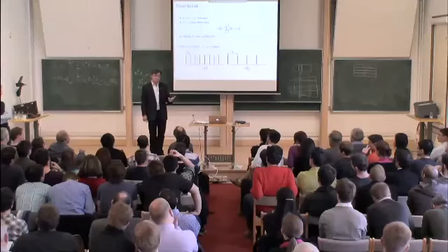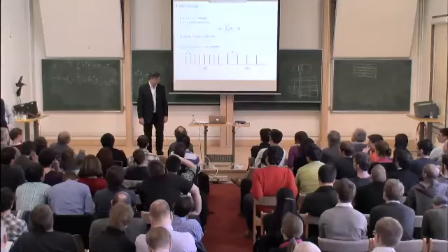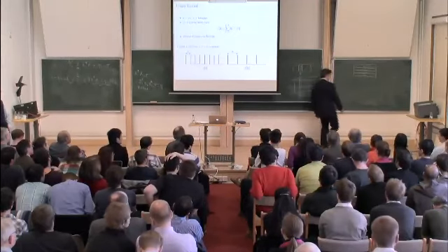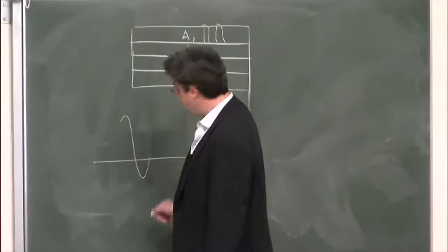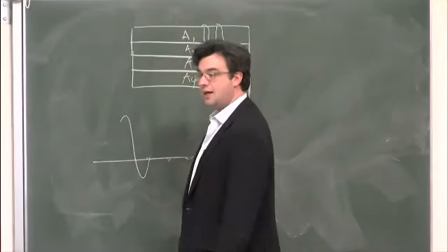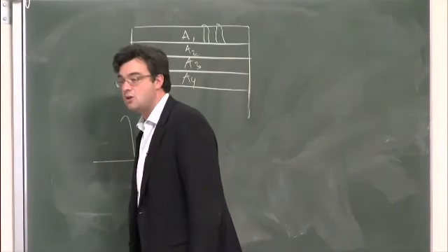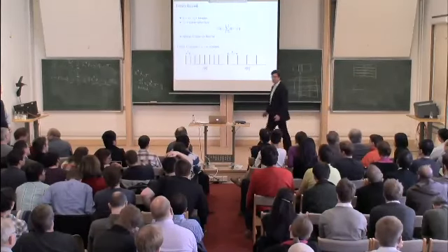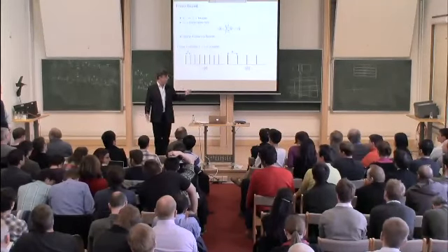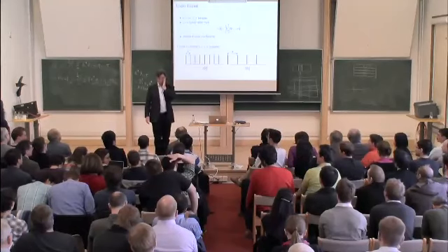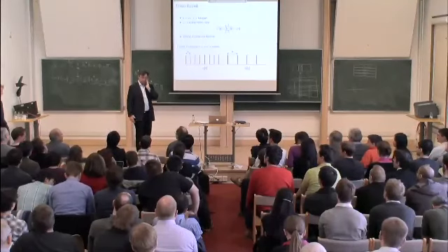What's exciting about this field is that we can actually design systems that take advantage of randomness. An ADC sampler essentially has a voltage, and each time the voltage crosses a line, boom, it decides to sample. But I can mess up the clock so that instead of crossing the line at equispaced intervals, it crosses at random locations, and then I have an ADC with very little work that samples non-uniformly in time. And when I have a high frequency spectrum, I can see that this works much better because I don't have these aliasing problems. It's less subject to signal assumptions.